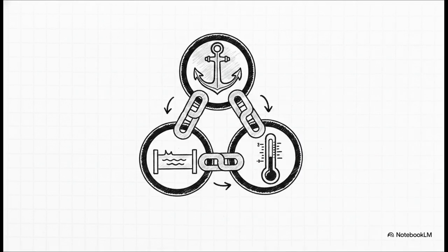Let's just slow down for a minute and lock in these golden rules of chilled water system behavior that we've mapped out today. First, when the load is fixed, your delta T strictly dictates your required gallons per minute. Second, any arbitrary change in flow will forcibly shift your delta T. The reality is, in a chilled water system, load, flow, and temperature difference are permanently linked together. If you mess with one while the load is fixed, the others are mechanically forced to respond. These variables are literally inseparable.